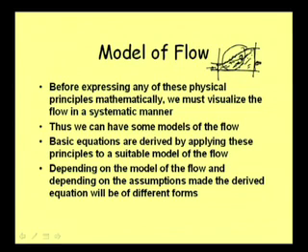We know the momentum here and the momentum here. In that case we can relate the rate of change of momentum to the external force without bringing in the complexity of energy loss in between. So probably the momentum equation will be better. Considering the situation, we need to select our equation.